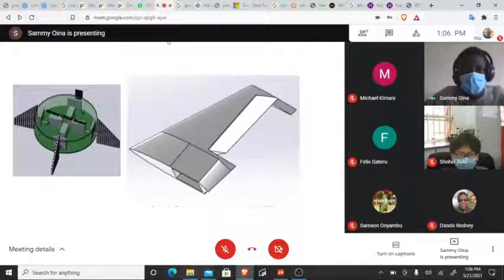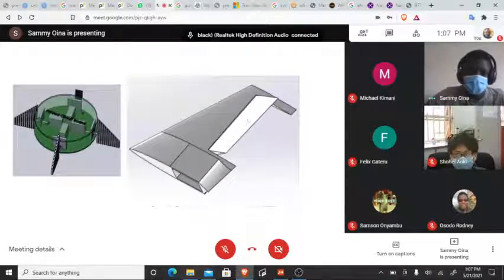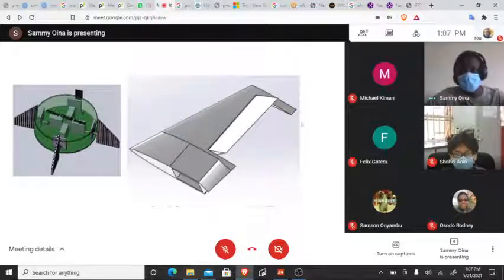So for movable fins, we can either move the tail fins, we can add some wings which you can control, or we can use canards. For canards, we can move the entire wing, or we can include a rudder system. The reason some people include the rudder is because moving the entire wing can sometimes cause vortices which will interfere with the tail fin. So the canards are the wings that are at the front of the rocket, the top side.